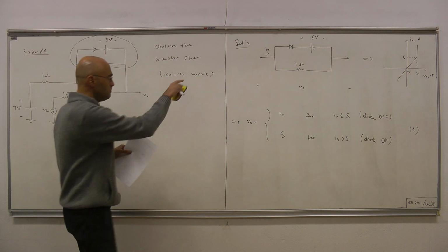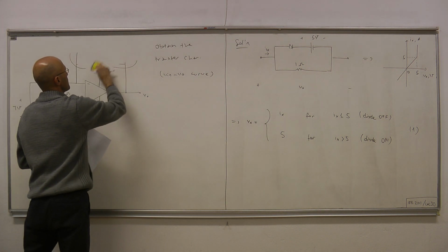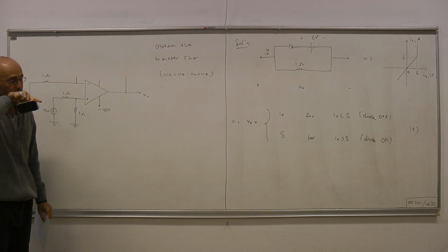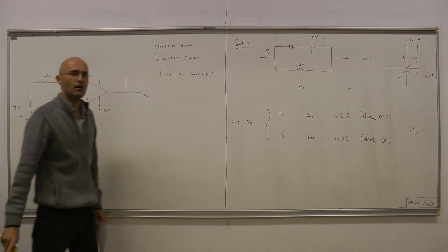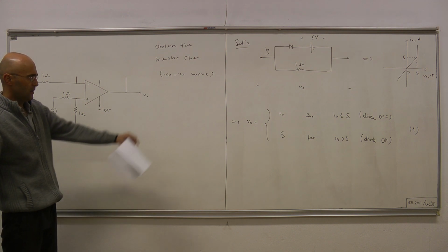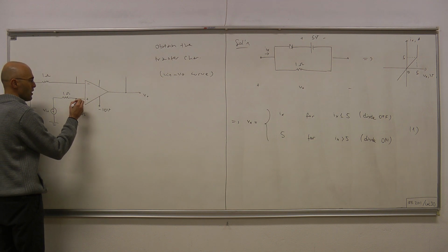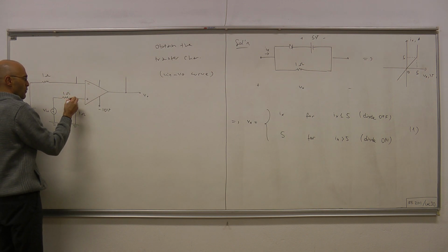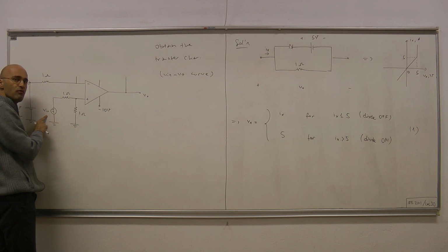Now, with that relationship, let's consider the following. Our circuit once again, replacing that one port with just a simpler diagram for which the voltage and current relation is there as we obtained. And as for V plus, since there is no current escaping into the op-amp through this wire, the voltage here equals, by simple voltage division, only 1/2 of V in.